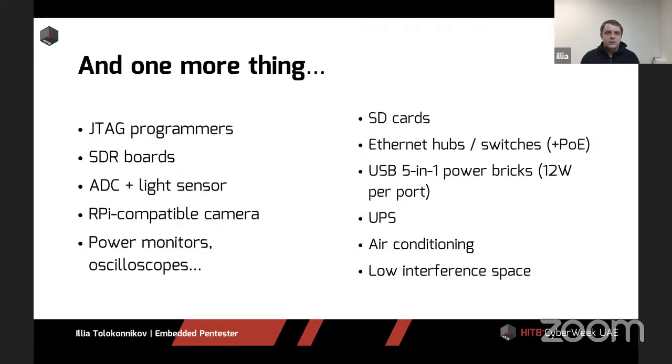We used SDRs at my work to fake GPS coordinates, kind of successfully. That's not actually entirely illegal, but there are some caveats. Without a proper license, you cannot stream those coordinates to a medium where other people's devices can hear that and act on that. So make sure you're in some kind of isolated space when you do that.